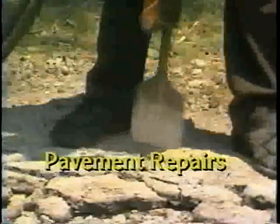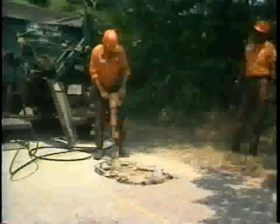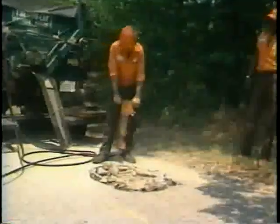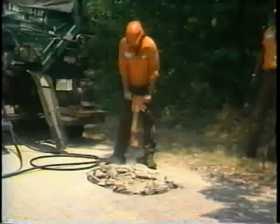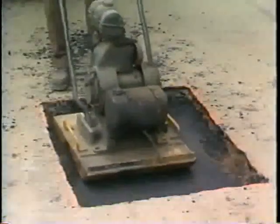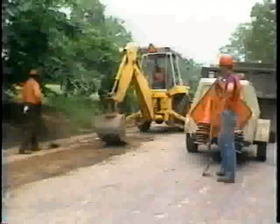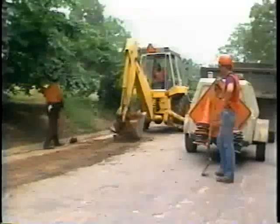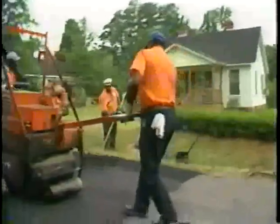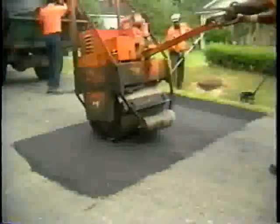Step 2 is pavement repairs. It is absolutely essential to repair the existing surface before the seal is applied. Typical repairs prior to an asphalt chip seal include pothole patching, full depth patching of badly broken alligatored pavement, and leveling of areas with rutting and depressions.